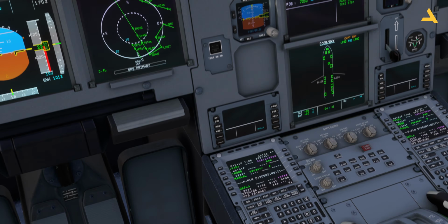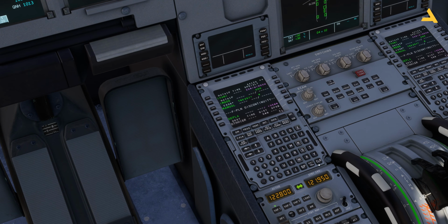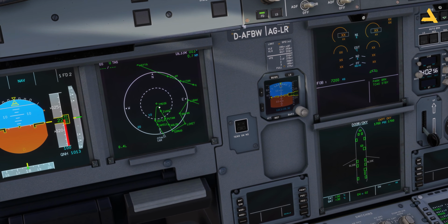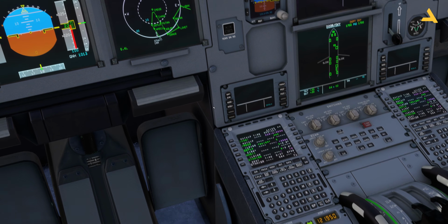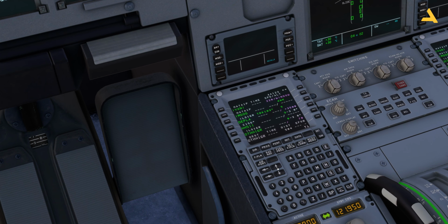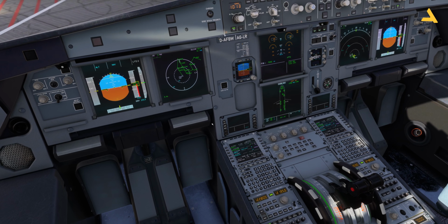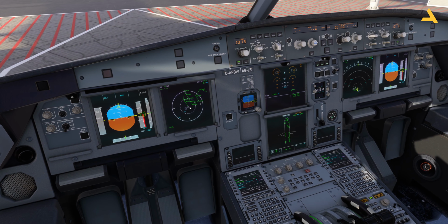Now, in order to delete it, you have to first of all delete this manual point. So if you want to clear the flight plan discontinuity, it will say not allowed because you have to delete the manual first. So let's clear this passage again. Clear it and then clear. First delete the manual and then clear and then delete the discontinuity, and now this will be a connected line, and now you will be able to fly this approach without any rocket science. That's a good one. And then in this flight plan, you also have a few points which are actually related to the missed approach.